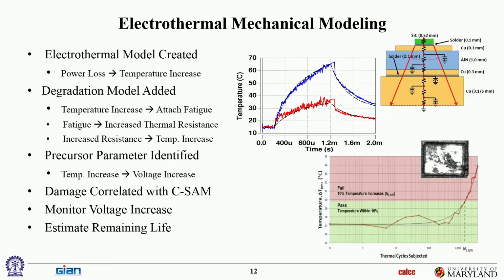So you already saw models like these. People who are doing the thermal management of power electronics are doing the same kinds of models that you talked about yesterday. So you build up thermal network models and then try to design your cooling system, your cold plates, liquid cooling. All of that is designed based on what the junction temperatures finally have to be.